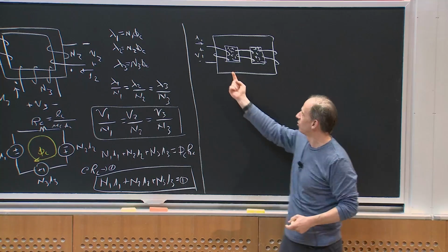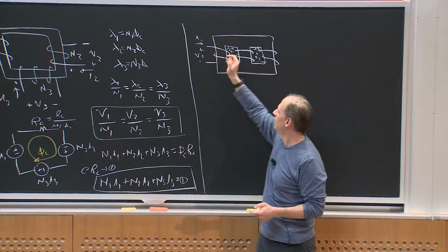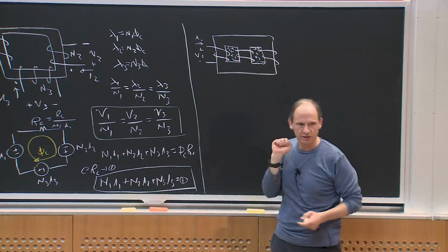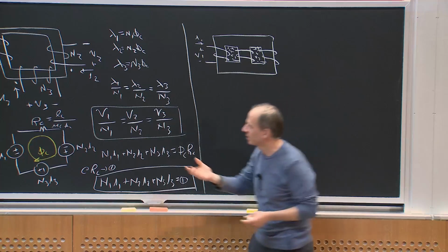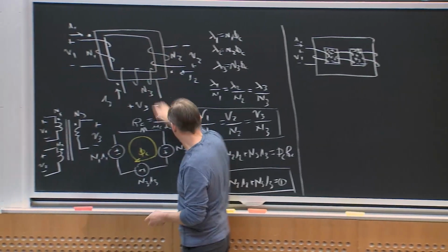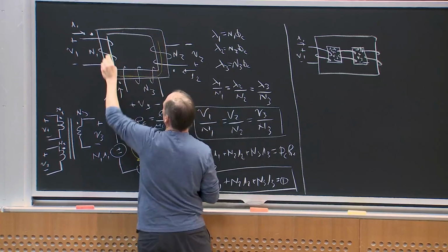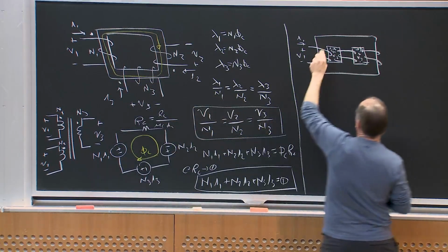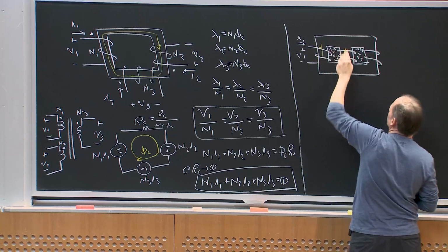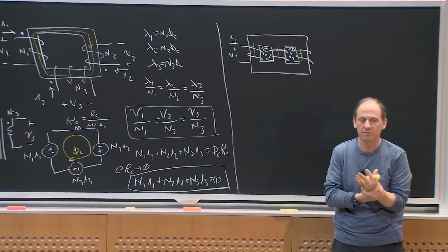That means that the flux going through this here, or the flux linkage here, isn't directly related to these 2 flux linkages, or it's not one-to-one, it's not just scaled. Because here I only had sort of one flux path going around the core. Ideally, here was my flux path, right? There's only one flux path. Here, there's a flux path here, and a different one here, and a different one here, and I get some constraints, but they're not the same fluxes.